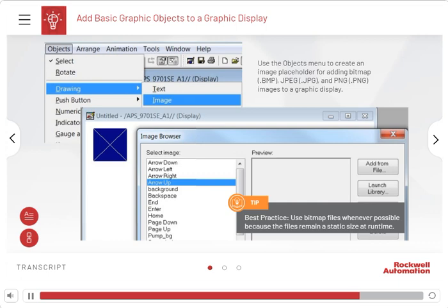When you import an image, FactoryTalk View software converts .gif, .tiff, .pcx, and .jpg images to the Windows .bmp format. Vector images in .dxf and .wmf formats are converted to FactoryTalk View graphic objects.